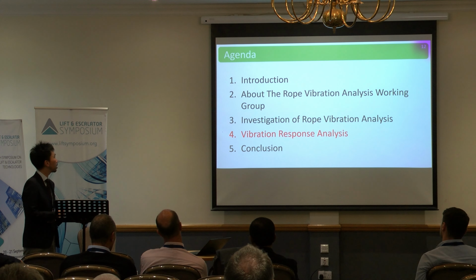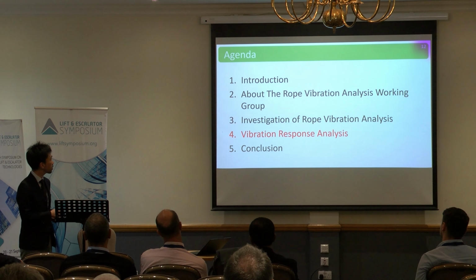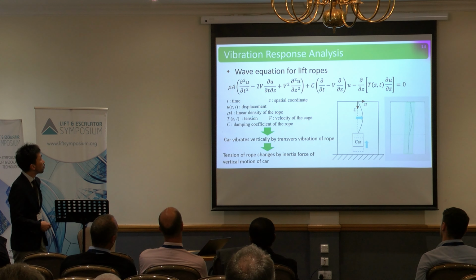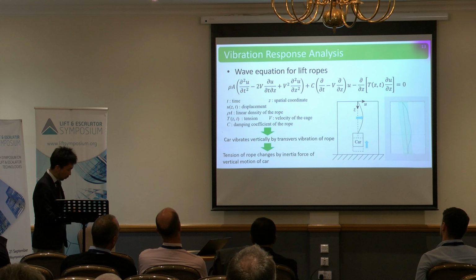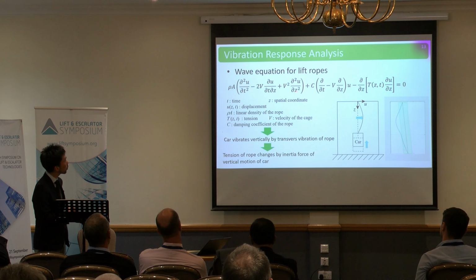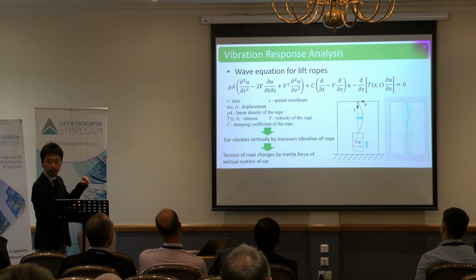So next, we conducted vibration response analysis based on the literature survey. The modified wave equation for the lift ropes was applied for our analysis. And this modified wave equation considers the tension distribution due to the weight of the rope itself.